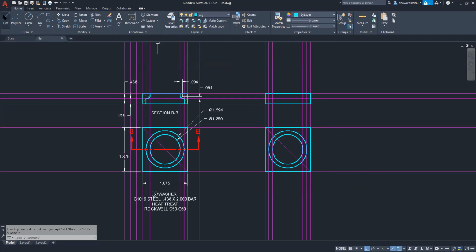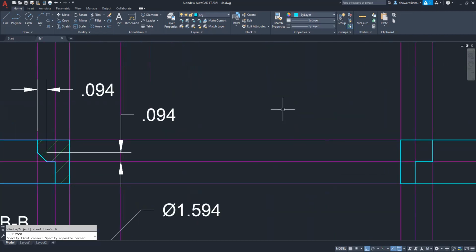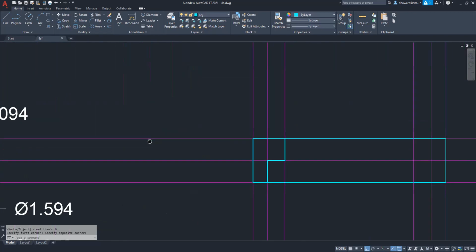And make this little stair step. I'm just going to do one and then mirror it. Now the thing to note, and we are told, is that there is a 45-degree chamfer on this that is 3/32 in size. So let me zoom in on that. There it is on one side, here it is on ours. It's 3/32 in its legs.